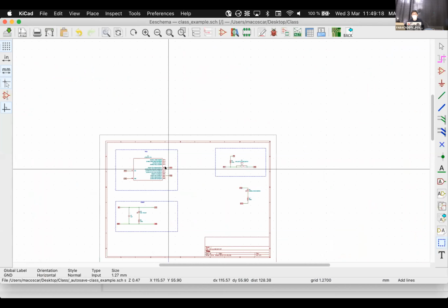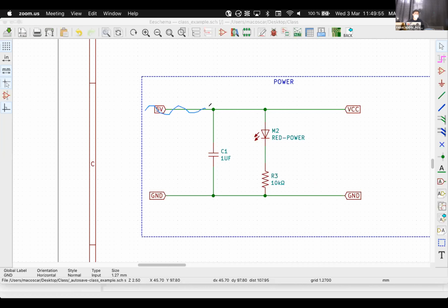normally, let me show you here. So if you imagine the voltage here, this could be, I'm not saying it is, but it's something like this. It's probably a little noisy. It's around 5, but it's not 5. It's 4.9, 5.1, etc. Normally, you want this to be a little bit more stable, and you put this capacitor here, so that it's like that.